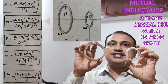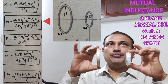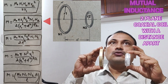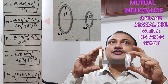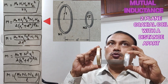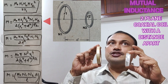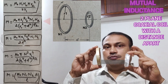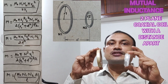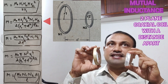If the system is such that they are separated by a distance small d, in that case the mutual inductance between these two coils will be equal to mu 0 pi r1 square r2 square n1 n2 upon 2 times within brackets (r1 square plus d square) whole to the power 3 by 2. This is the formula for mutual inductance for this system, where the radius r1 of this coil is greater than the radius of the second coil.